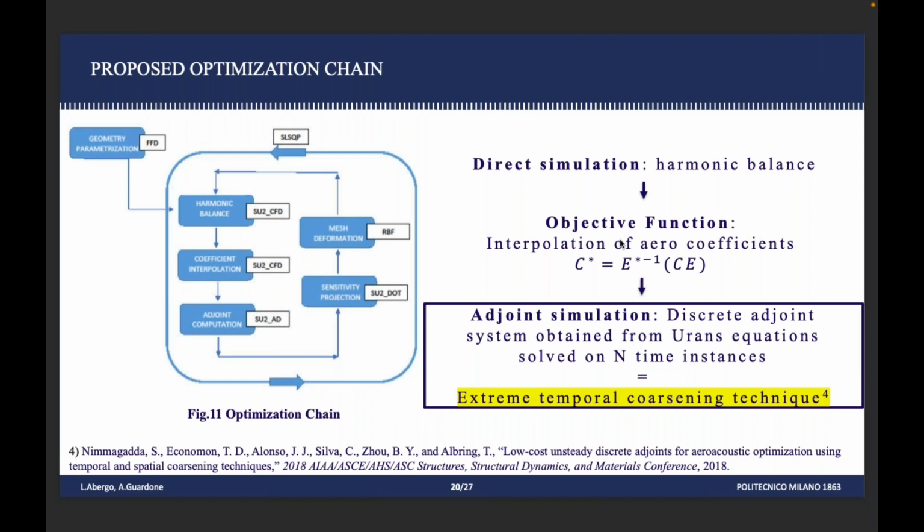But my concern is virtual memory allocation, because the memory allocation with harmonic balance scales linearly with the number of frequencies that we are going to solve, and we all know that with direct differentiation, also in that case, the virtual memory is augmented by 3-4 times. So combining these two effects, my concern is if we need to simulate a very big grid, maybe RAM is going to be a bottleneck.